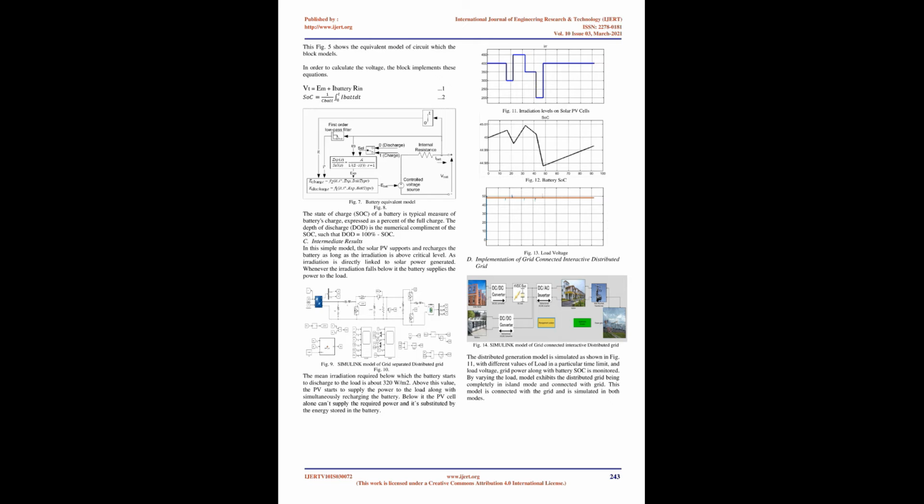These are then connected to converters which convert the voltage to the supply voltage. Converters. DC to DC converters and DC to AC converters are used to convert the power to the required value, depending upon the need for storage or usage. Storage element. Battery banks are the only solution currently, but many other unconventional sources of energy storage are being explored, like flywheel energy storage, thermal energy storage, etc. Control system. The control system is designed based on the values of battery voltage, SOC, irradiation along with the type of customer load behavior.